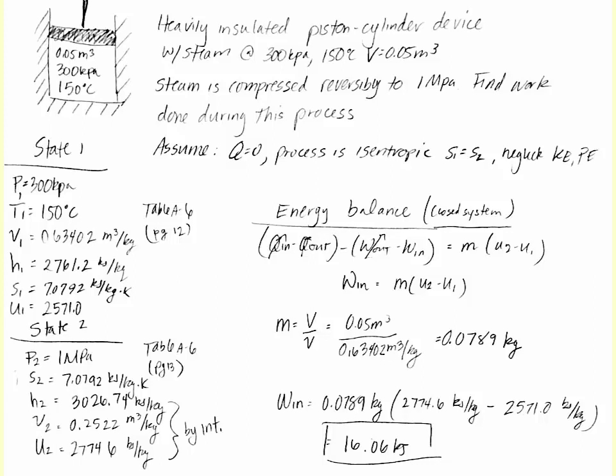Why do we use that particular balance? Because it's a closed system. So if we look back to the derivation of the energy balance for an open system, it's because we have flow work. So the base energy equation is the energy into the system minus the energy out of the system is equal to the change in energy of the system. Okay, so energy is coming in by heat and work, and energy is changing. The energy that is changing is represented by this change in internal energy.